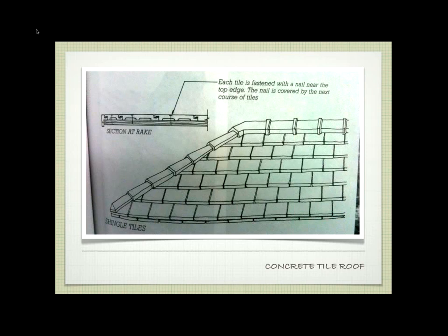These are concrete roof tiles, which is also common, especially in fire areas. Same concept, it's just a concrete tile that's been cast in a particular shape. That's used, right, and they look more like slate, really. They're usually a little bit thicker. They have nail holes at the back. Some of them have grooves that interlock with the one next to them, which helps them stay close together. Again, heavy, high first cost, but they're going to last for a really long time, which is a big benefit.